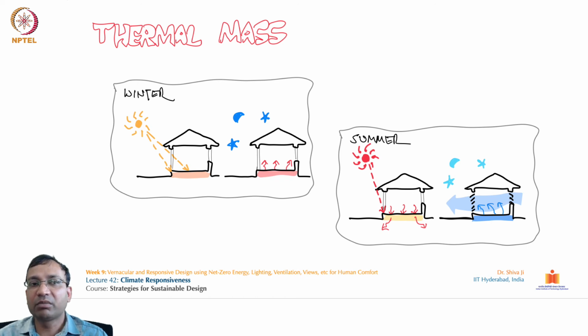You can see over here, this fiberglass insulation has the lowest thermal mass capacity of only 9.2 kilojoules per cubic meter Kelvin. And if you see, water has the highest capacity. So when we need the thermal mass, maybe we can go for these materials from the top: water, granite, concrete, sandstone, and clay tiles, etc. Where we do not want it, maybe in those places we can go from the bottom up.